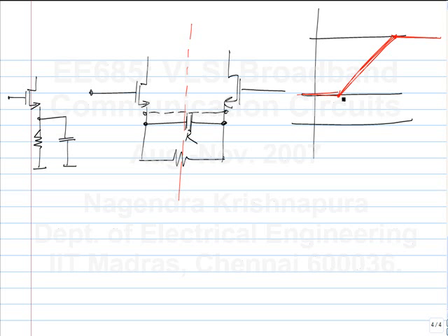And the 0 is a real 0. This is not a purely imaginary 0, right? The 0 of this circuit lies on the S plane here, not here. So there is no frequency of a sinusoid for which this impedance looks like a short circuit.